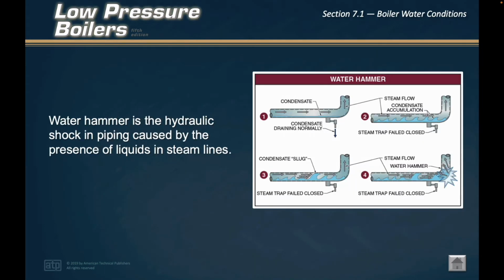High surface tension is a boiler water condition in which the surface of the water is strengthened by a layer of impurities. High surface tension restricts the release of steam from boiler water and is indicated by a rapid fluctuation of the level in the gauge glass. The gauge glass fills and empties rapidly, indicating bubbles trapped or foaming in the boiler water. Care in opening the steam valves prevents carryover caused by sudden pressure changes. In addition, priming and carryover or a failed steam trap can lead to water hammer. Extreme water hammer can cause steam lines to burst.